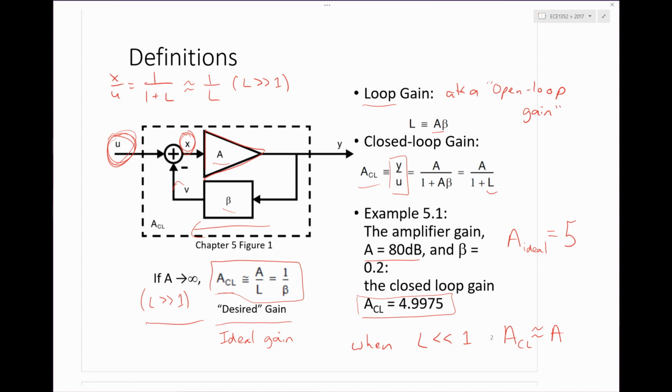And in particular, because A is the circuit that's providing gain, the only way we're going to get gain is by using active components, transistors. We can't get gain from just resistors and capacitors. So there's going to have to be transistors in A, which means it's for sure going to be nonlinear for large enough inputs. So this is a great way to use those active components.